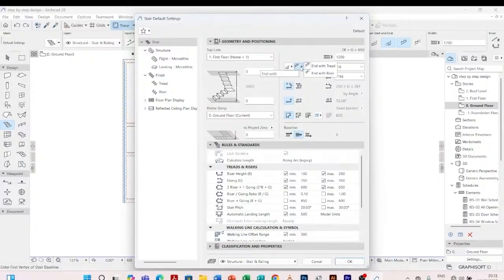If we start with the riser, we shall end with the tread. And so the setting 1.2, and this is 1.2. You can change. You can have yours at least from 1.2, 1.5, 1 meter according. Since it is automatic to our first floor, it calculates the number of risers, so there will be 18. And these are also settings of the depth. If you want to change them, you can do it here. You can make maybe 300.